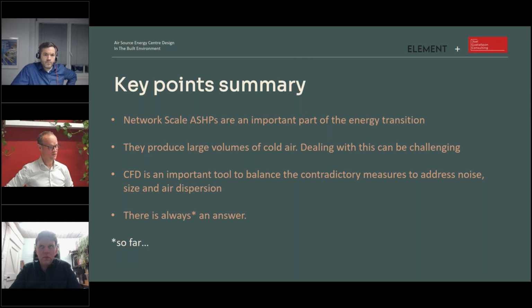But we built a one-to-one factory mock-up prior to delivery to site of the temporary heat pump, the exact dry air cooler configuration. On the back of the modelling I'd pushed for a physical separator that was horizontal. The architects had some pushback. We tested it on the factory acceptance test, and I got my way following the factory acceptance test, with temperature measurements and with smoke testing at the same time.